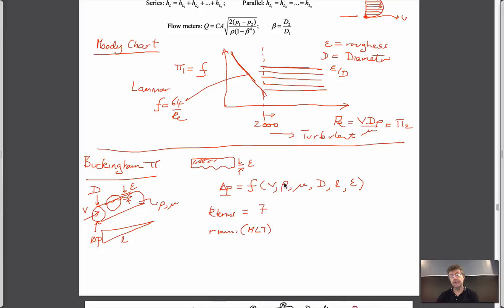Mass, density per unit volume, so for sure we got mass. Length, well, I've got lots of terms with length. And velocity for sure is length over time. So we have all three represented. So this is equal to 3. So the number of pi terms is going to be equal to 7 minus 3, which is 4.